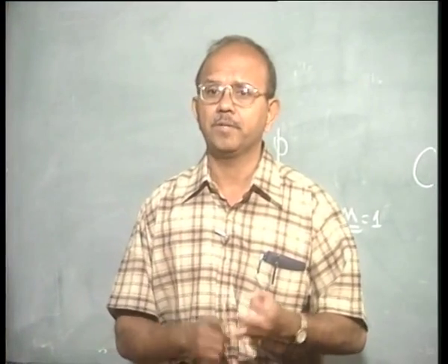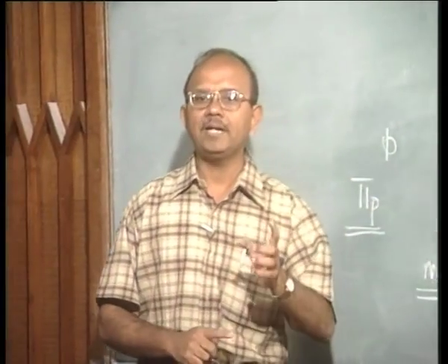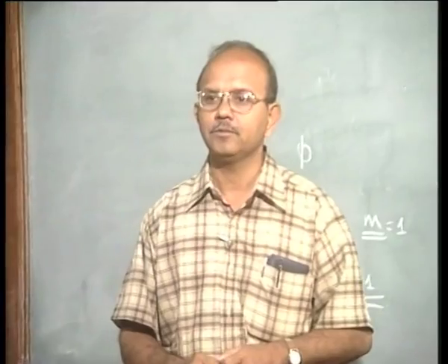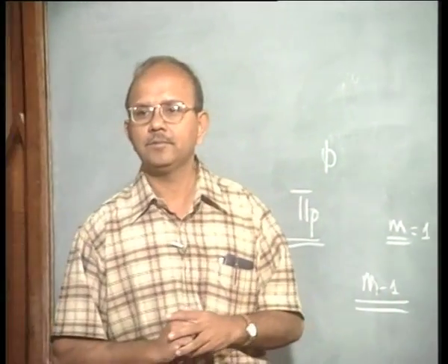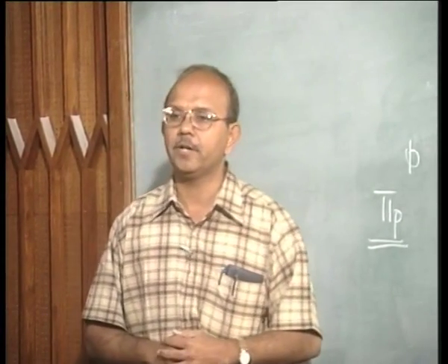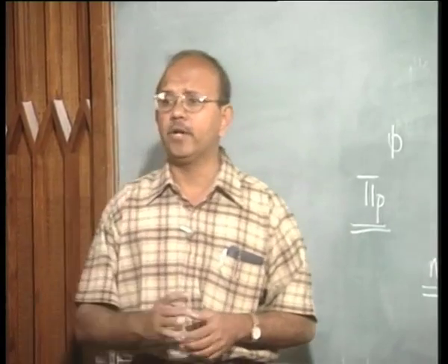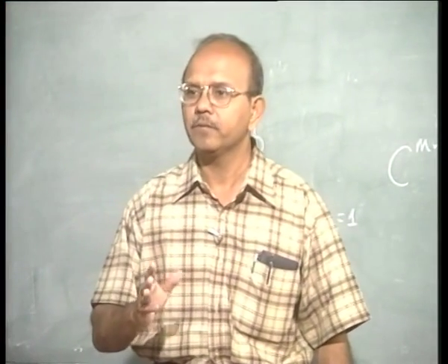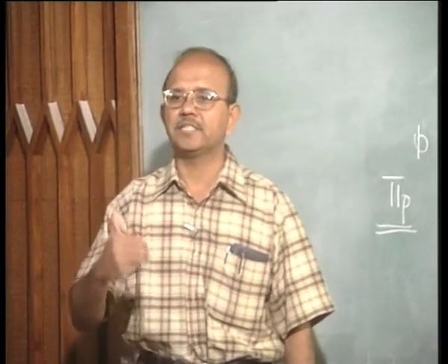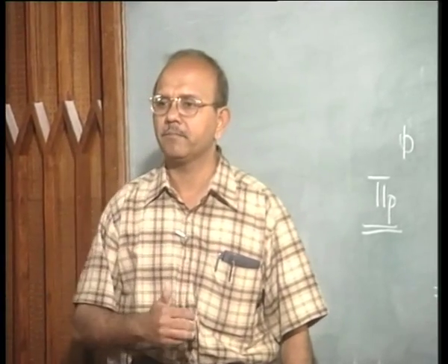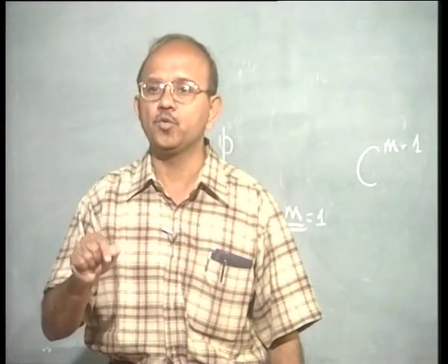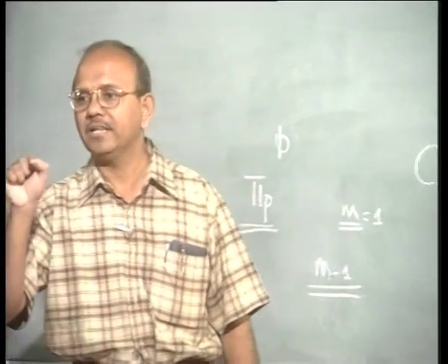The third condition becomes very important. When I define an element using an interpolation function and put this element in a mesh, and apply a boundary condition such that I specify the differential up to m minus 1, for example, in this case, suppose I specify constant strains, or constant displacement or constant strain, then the element should be capable of taking that differential.